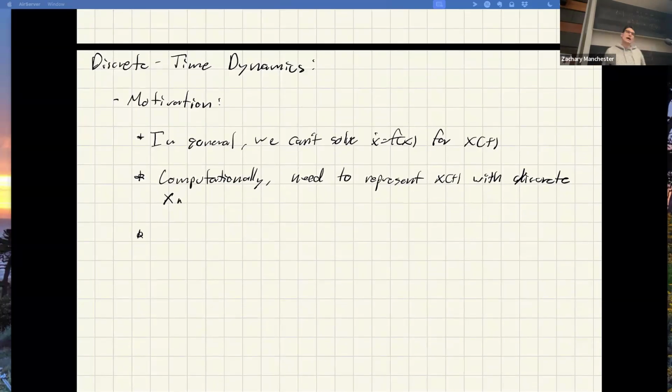The other fun fact about this is there's a sense in which discrete time models are more general or can capture some behaviors that continuous ODEs can't. In particular, I teased this last time, in a lot of robotic systems we have non-smooth behaviors like impacts, and those, strictly speaking, are non-differentiable. So if they're non-differentiable, I can't write down x dot, right? There are discontinuous jumps.